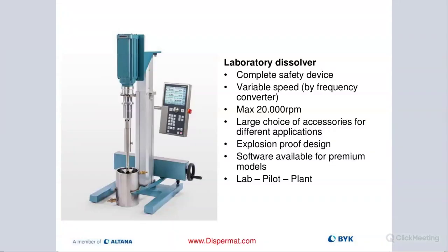H2 is the upper threshold, and basically that means that once I set H2, the operator will not be able to lift up or raise the shaft beyond that point, H2, while the blade is spinning. So it would automatically stop at that reference height, and then you have to power down the machine to be able to go above that threshold setting. You can freely move in between H1 and H2 and oscillate and do anything you want, but you'll never be able to find the blade spinning above the H2.